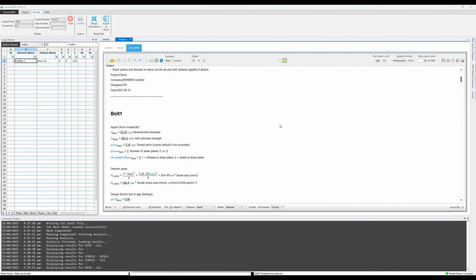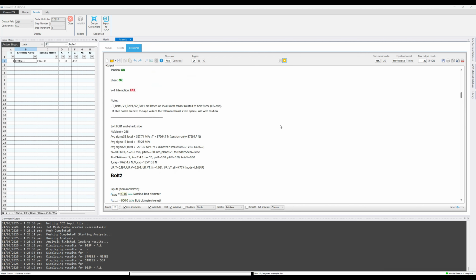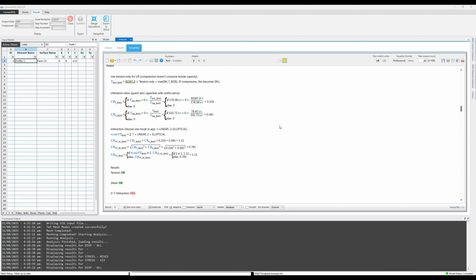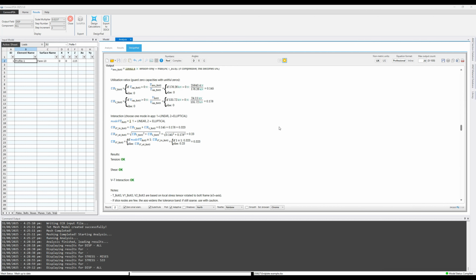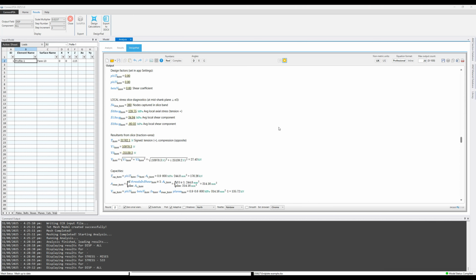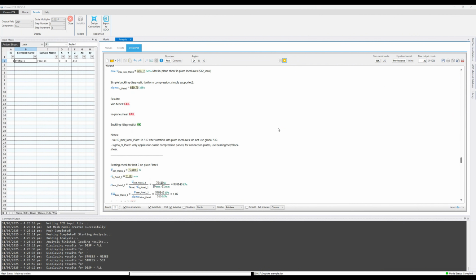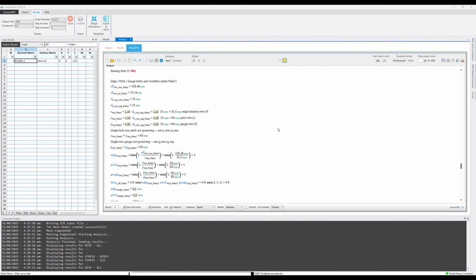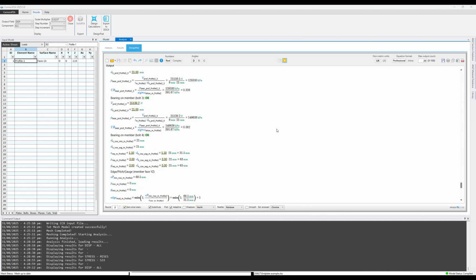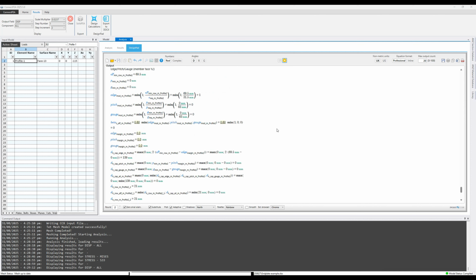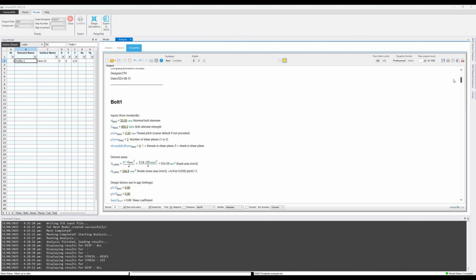Once we've got all of that, we can plug it into the calculation engine or design pad, which is a modified calc pad variant that we use, and it'll give us a summary of the elements with their utilization for tension and shear, and then it'll do a detailed calculation of each member, the bolts, the plates, the profiles where the bolts interact with them, and show us in detail using a calculation template on whether those pass or fail the checks that we've set up here. And you can, of course, customize those calculations to suit your own narrative and your own outputs and criteria that you want to check. But by default, this is what it does. It does quite a lot of work, and it presents really well.